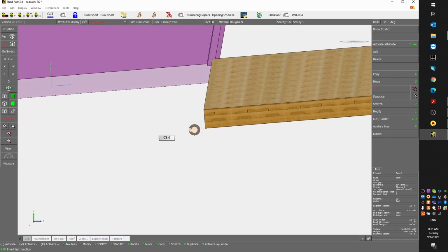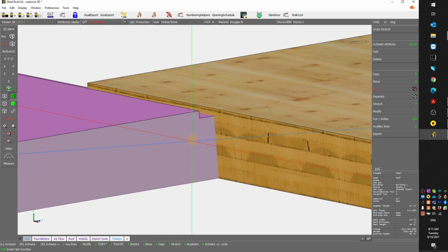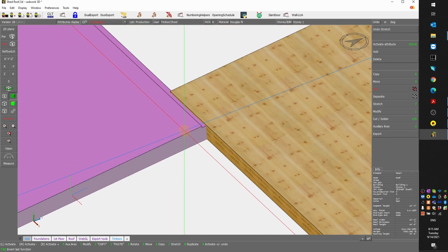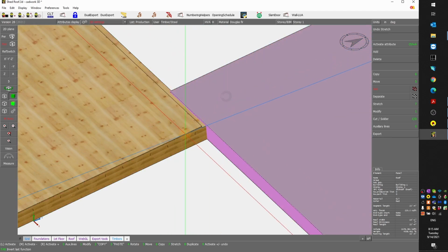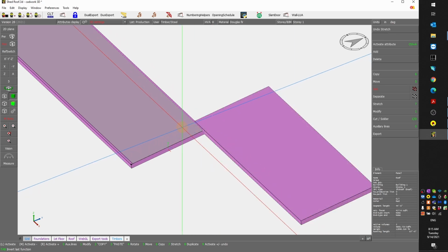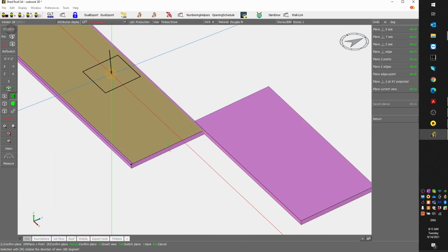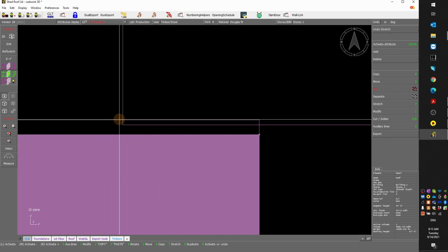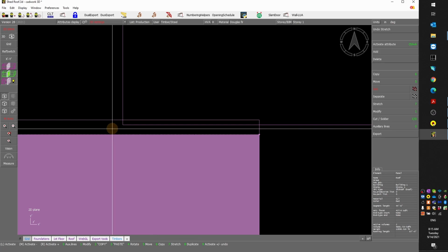And here what I'd like to do, and again it's a little bit tricky, I want to cut from the top because this panel is cut 90 degrees, so it's not plumb. So I need to cut again this guy and make sure it's got an eighth of an inch. So I select the top of the panel. I can go to a 2D plane, right click, and here I'm gonna set it again at an eighth of an inch. So E, an eighth,